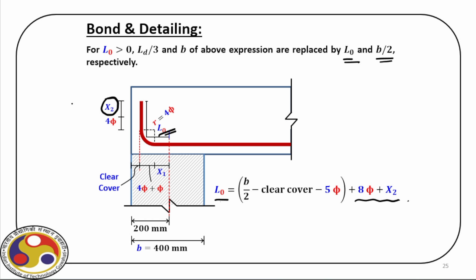So you can see how we can provide sufficient bond length and the anchorage so that there is no slip between the steel reinforcement and the concrete. This is very important, and we have also discussed where we can curtail the rebars, because along the length of the beam bending moment will vary, and therefore if we design the section based on the maximum bending moment, as we move along the length of the beam the bending moment will vary, and accordingly we can curtail the bar, but we have to provide sufficient length of the bar between the theoretical cutoff point and the actual cutoff point.